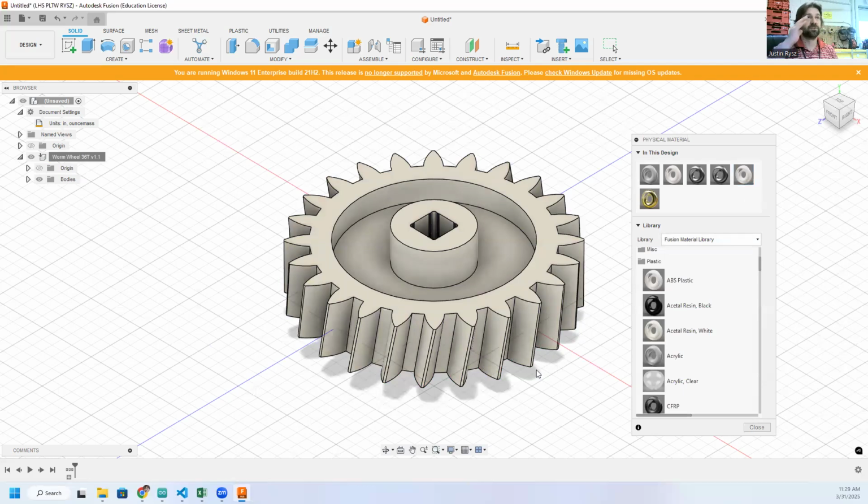So here's the trick. I'm going to take a material that's pretty close. Technically, we can do any material, we would just be changing a whole lot more. And I'm going to change that. Do I want to do, yeah, ABS is good. Okay, so what I'm going to do first is right click on this and click duplicate. So now I have ABS plastic 2.